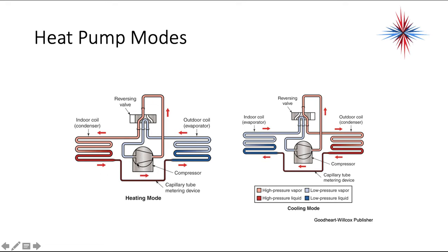The key concept is the compressor never changes direction. It's not like we change the direction of the compressor. We just reroute the suction line and the discharge line. So when I take my pressures on the discharge and suction line, regardless of the position of the reversing valve, I am getting true suction and discharge pressures. So again, the reversing valve is the heart of the controls of a heat pump system.